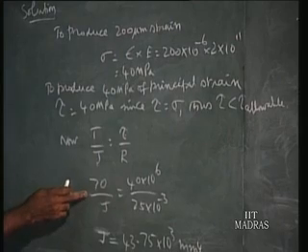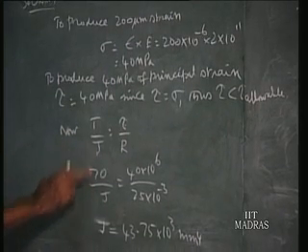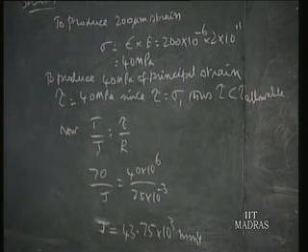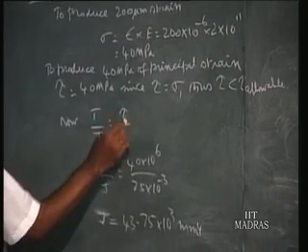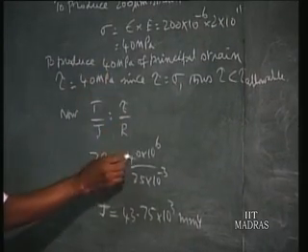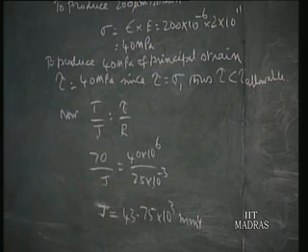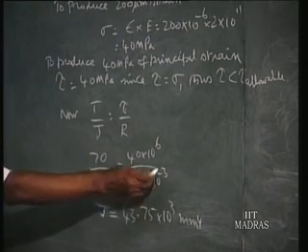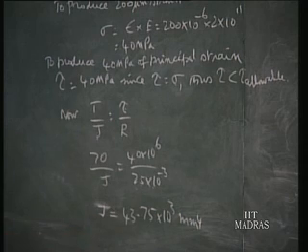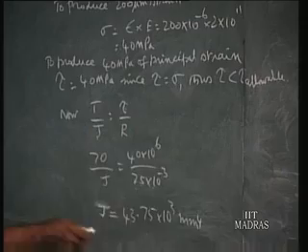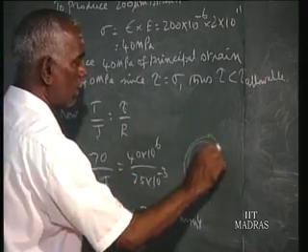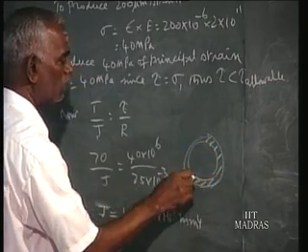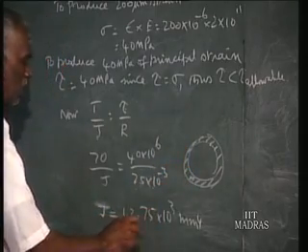So T here is T maximum, 70 Newton meter, and J is the polar moment of inertia of the cross section area, and the shear stress is 40 megapascal. The outside diameter is given as 50 millimeter, so that gives rise to a radius of 25 millimeter, that is 25 × 10^-3 in meters, giving a J of 43.75 × 10^3 millimeter to the power 4. That is the polar moment of inertia. So the annular area should give rise to a polar moment of inertia of so much.